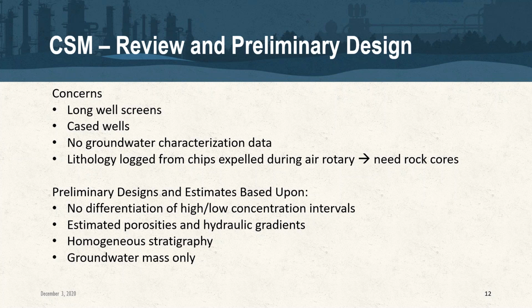That's going to show us where groundwater zones are, whether they're receiving zones, what type of fractures we have. Are we changing lithologies here? Are we changing fracture networks if we're moving between different units? Are these limestones, shales? If we're moving into harder rock, we really need to have a good resolution on how we come up with the design.